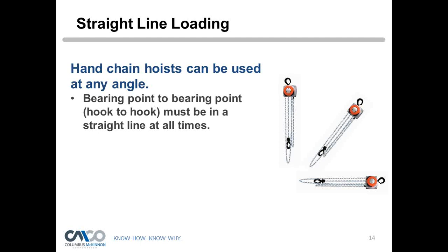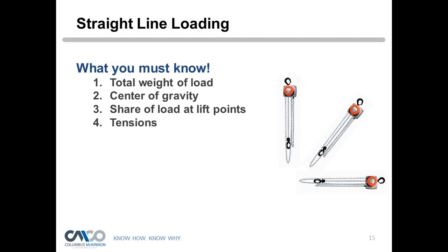Now, you may be using the hoist in this manner because you don't know where your center of gravity is. So you're either going to have to know what your share of load is on your connection points or your center of gravity. You're going to have to figure out one or the other. And to do so, you can get scales, or look at prints. If you know where your center of gravity is, you should be able to figure out where your share of load is. And again, we have another webinar that we just did last month all about the center of gravity and how to calculate your share of load. That's another webinar you can watch that goes into great detail on how to do that.